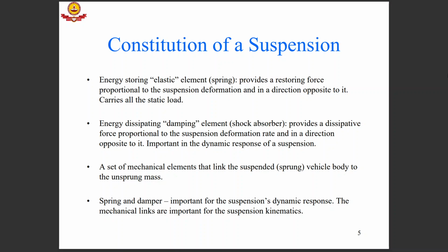So the spring force would be k into x, and the damping force would be c into x dot. So the spring and damper are important for the suspension's dynamic response, and its kinematics is governed predominantly by the linkages we have.